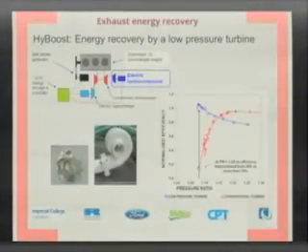This is experimental information. We have been able to shift the peak from that conventional design to that unconventional design, achieving an improvement which is visible in that graph, and which is being tested, and is part of a larger project called High Boost, I should mention, where we put this downstream of the main turbo to get a few more kilowatts. This engine is about 80 kilowatts. We're getting about 1.5 kilowatts extra.